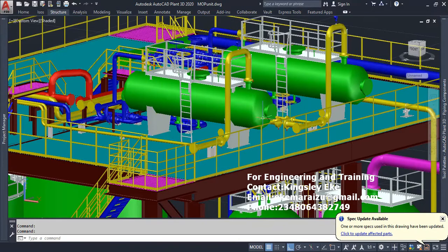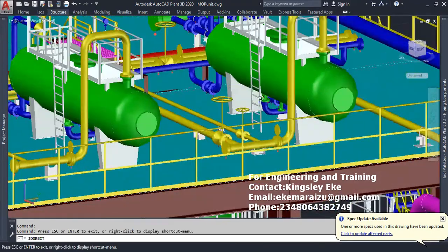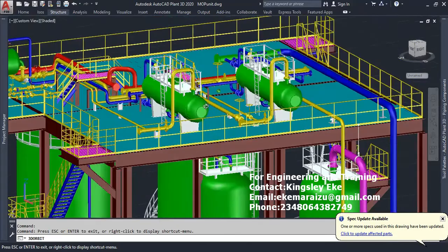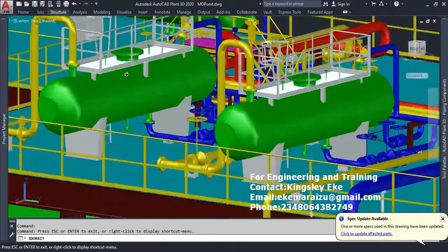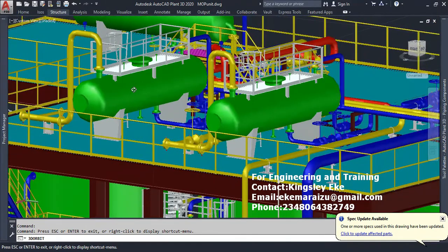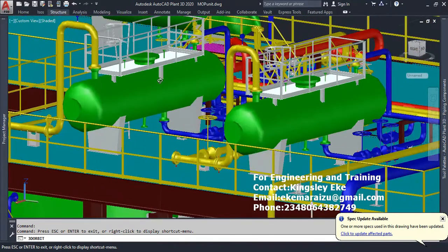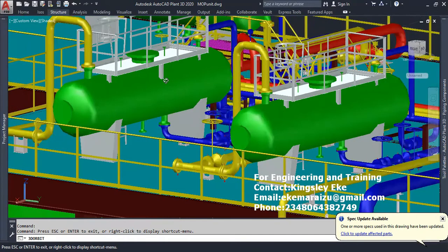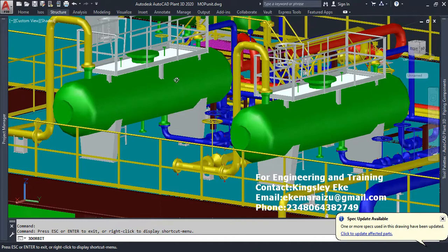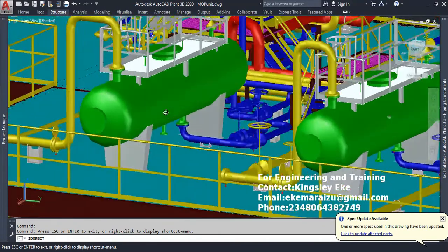The mechanical engineer will take this information and carry out detailed mechanical design of this separator using PV Elite. One of its results that serves as an input to the structural engineer is the weight of this vessel. In carrying out detailed mechanical engineering design, we factor in all load cases, ensure that the erection load case, the shutdown load case, the operational load case are all satisfied. The weight from this vessel is given to the structural engineer to carry out his own design.